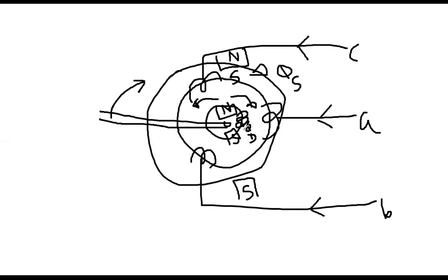So you need the help of the damper winding. Keep in mind, initially there was no damper winding. But in the case of the induction motor, from the beginning there are three sets of coil. And this is the extra arrangement. Once the motor has started rotating, is there any role of this coil? No, there is no role of that coil. It does not matter, but initially you need it. So that's why it is called the starting coil, to start the synchronous motor.